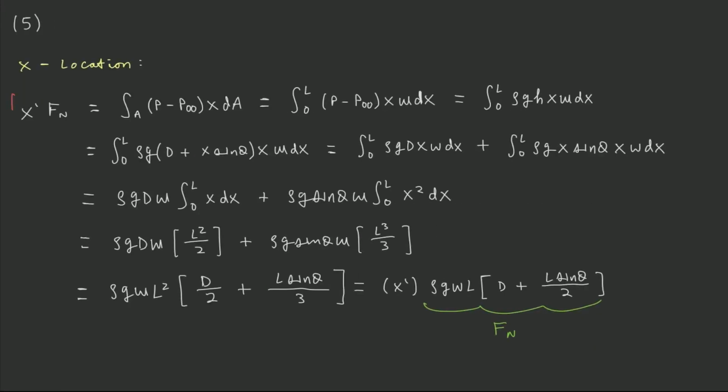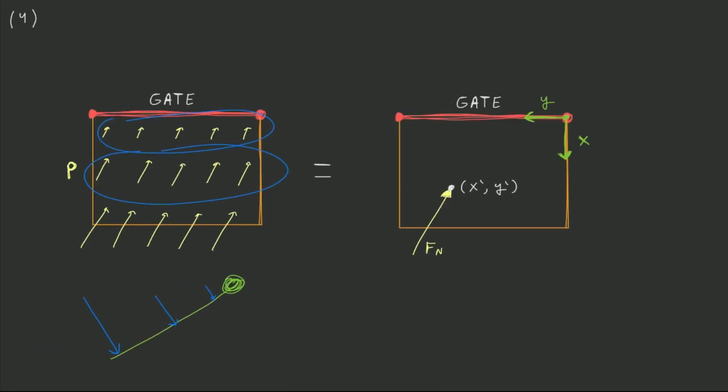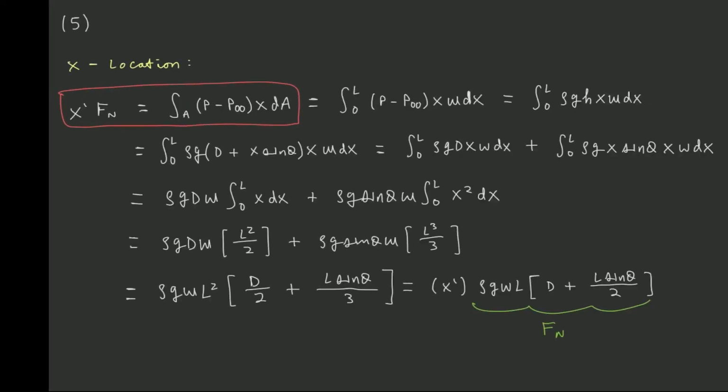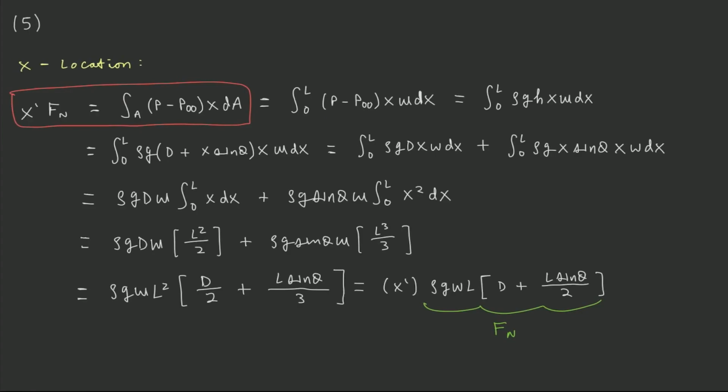So what this primary expression right here is really saying is, if we go back to the previous slide, we could see that this pressure distribution, as shown right here, is creating a moment about this y-axis, right? So this pressure distribution down here is creating a net moment about this y-axis. This is what this integral calculates, that moment about the y-axis created by the net pressure distribution.